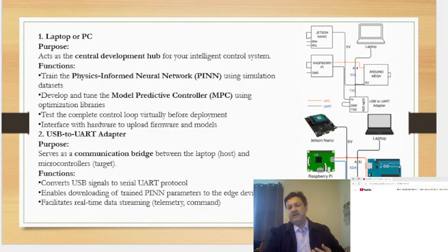What is actually happening? One is the data that the model I'm giving. This is going to the Arduino, then it is going to the Jetson Nano. It is getting data interface from the sensors. This Jetson Nano hosts the on-device MPC optimizer to perform fast control decisions. So whatever has been told in the model according to the data, this has to take, using the on-device MPC optimizer, to perform fast control decisions. And this Jetson Nano sends the final control command to actuators via microcontroller or GPIO.